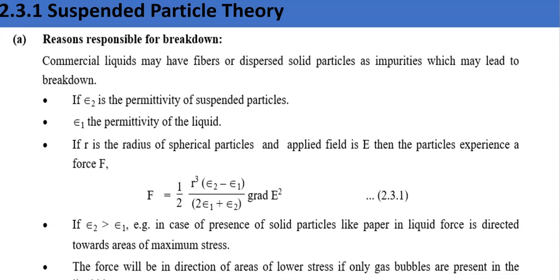Because every theory considers some different reason, and as the reason considered is different, the factors affecting breakdown voltage are also different, so you have to keep that in mind. So here let us see the suspended particle theory. As it is a suspended particle, it means something is suspended in the liquid, and of course it will be impurity only, because I told you commercial liquid has impurity. So in the suspended particle theory, some suspended impurity in the oil is considered.